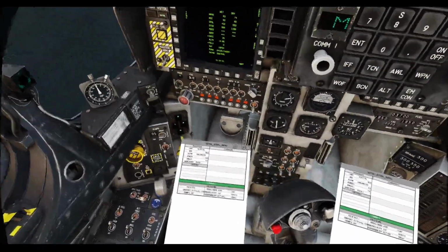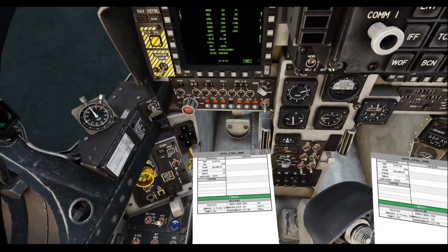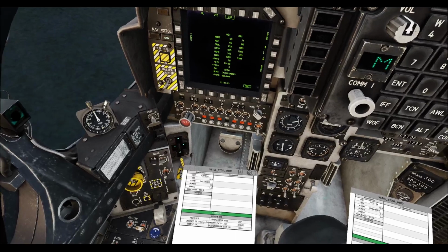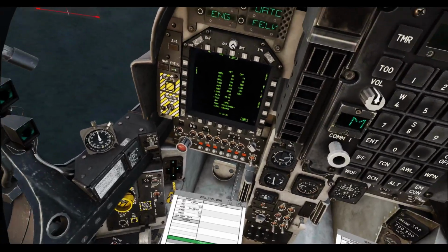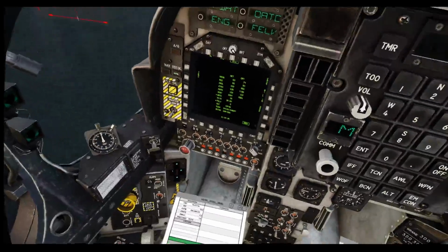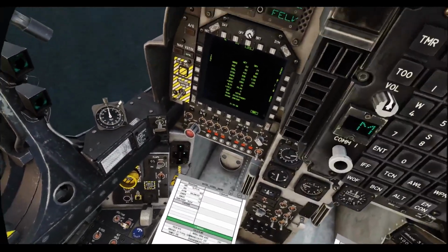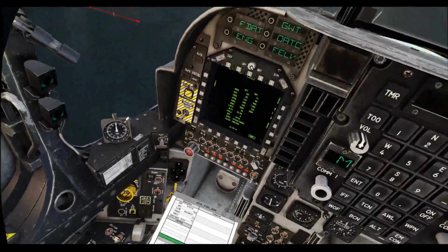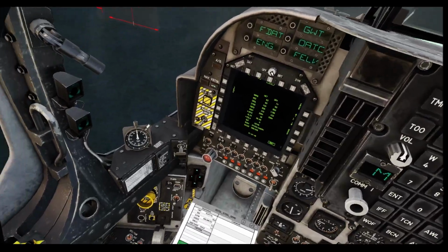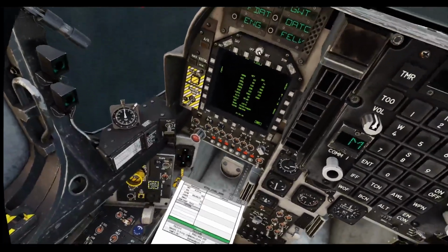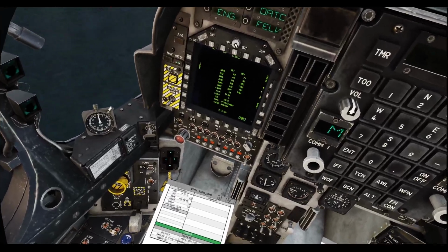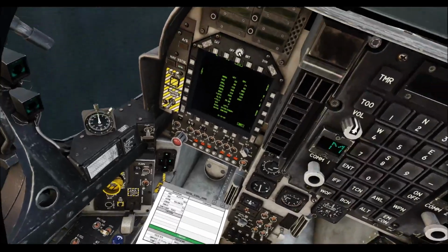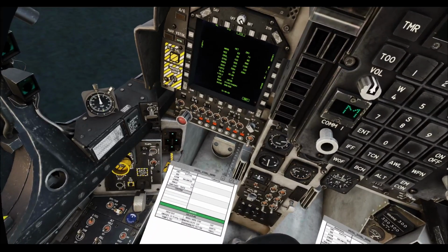And that is that. Now, at the bottom of the VRS page, we're going to hit abort, get our abort speed. So in this case, we are going to do a dry takeoff. So that's going to be 103 knots. If we get above 103 knots and we want to reject the takeoff for whatever reason, we either need to just eject, or we need to get the aircraft clear of the ground, get it pointed in a safe direction and eject, or potentially, if we've got the performance, do some sort of land ahead recovery if safe to do so, or a circuit recovery if we're able to do so. Nine times out of 10, if you need to abort the takeoff for whatever reason, you're above the abort speed, you are going to need to eject. It's as simple as that.